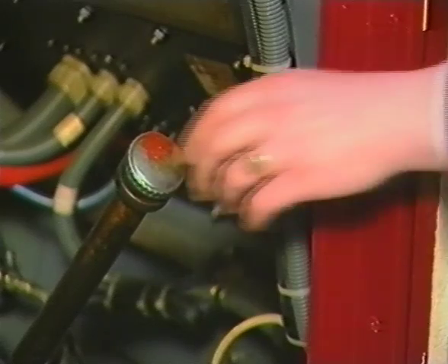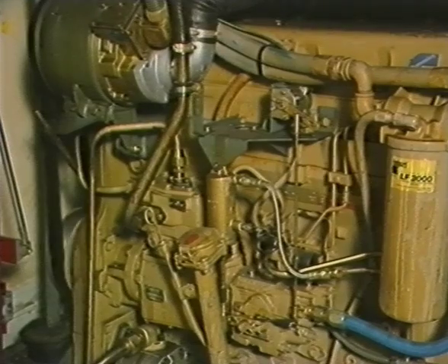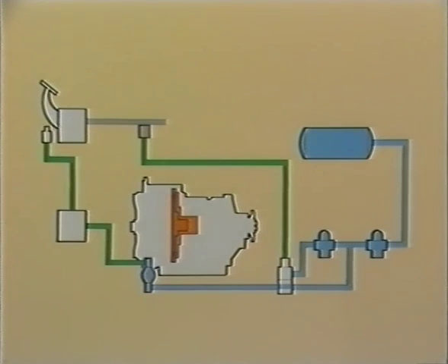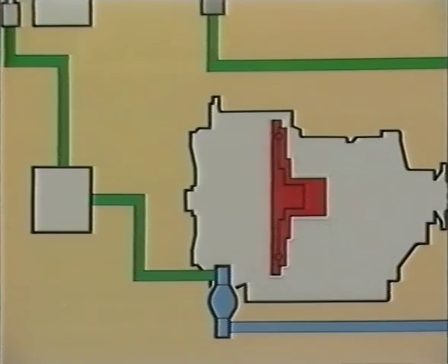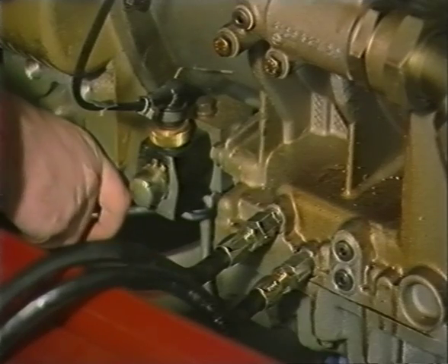If the retarder does not operate, you should first ensure that the oil level is correct and that the load sender is in order. It should be noted that if the load sender is indicating throttle, retarder operation is inhibited. If the retarder still fails to function, it may be a failure in any one of the following: the switch signal to the panel, the control panel, MV1 solenoid or wiring, air supply, or finally a hydraulic fault within the gearbox. To continue, first establish that there is an air supply to MV1.